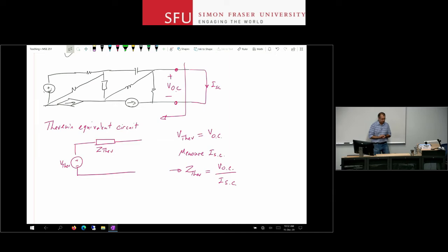There is a different way of doing the same thing, finding the equivalent impedance of whatever is behind that port, that we actually use more often in this course because we're dealing with nonlinear circuits, and things are basically not that easy. If you open circuit and short circuit different nodes arbitrarily, you may actually put devices in operating conditions that are not desirable. Even confusing those things may create some challenges later on. So we have a slightly different method for doing the calculation of the Z Thevenin.